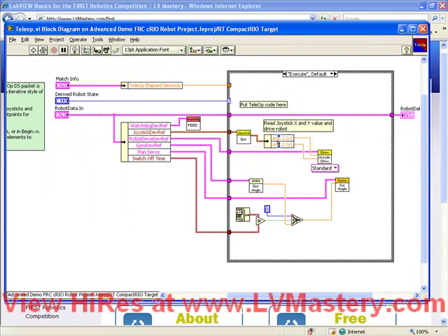I've had the opportunity to observe a lot of new LabVIEW programmers, and one of the most common problems I see is very simple to solve, and it's just about wiring techniques and wiring style. Let me give you an example. Let's delete and then redo the wire from the switch off time in the unbundle by name function to the bottom terminal of the comparison function.